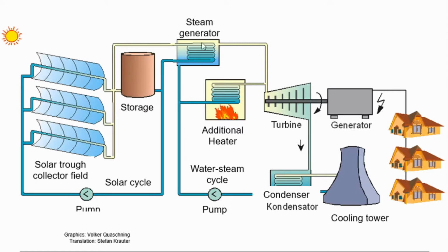You produce the steam then with a heat exchanger, and the high pressure steam goes inside the turbine, powers a generator, and you power some houses. Then you liquefy by condensing the steam here. The pipe goes through here, because it was originally German and I put the English expression over it. Then you go via a pump, and this increases the pressure. It consumes quite a lot of energy because you have to create a high pressure here. And then additionally pressure is created by the steam generator here.